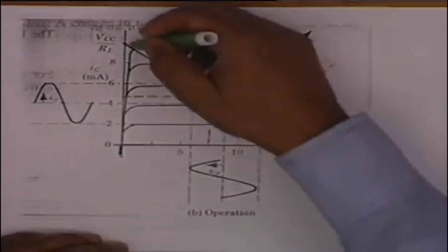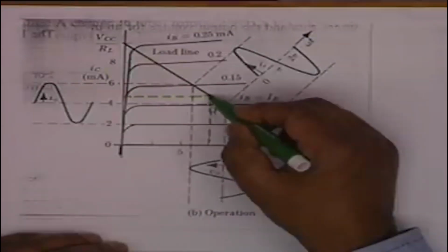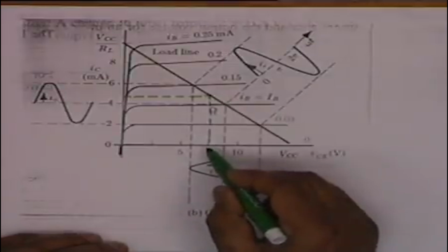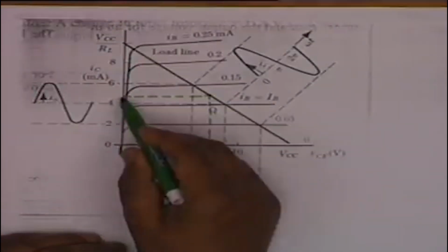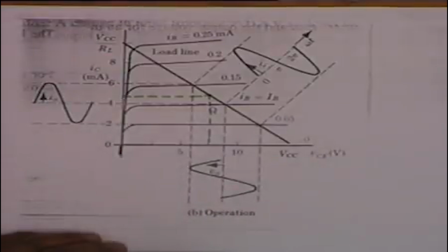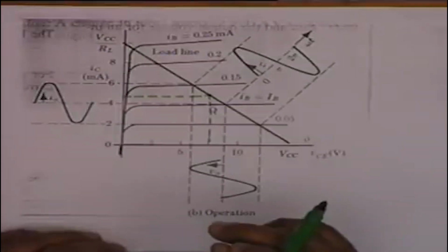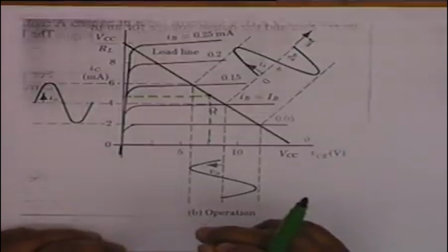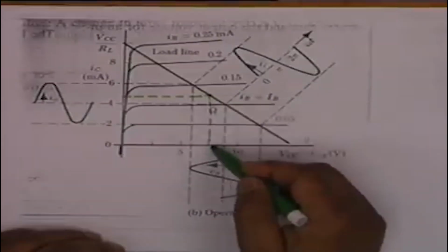The DC load line and AC load line for this example are the same, and it is this orange curve. The Q point is here at 7.5 volt DC and 5 milliampere. Can you tell me what is the maximum possible voltage swing? If this is 7.5, the DC load line and AC load line are the same. In other words, there is no capacitor taking to a load.